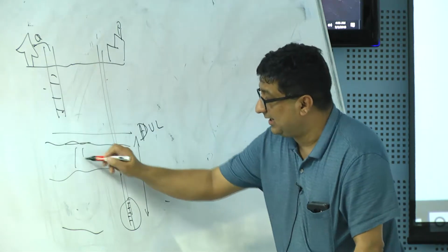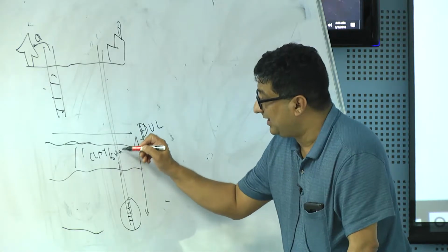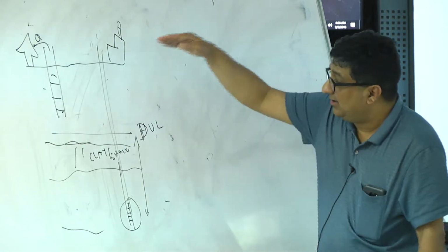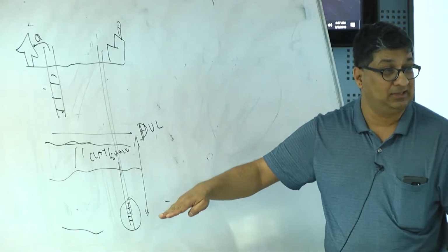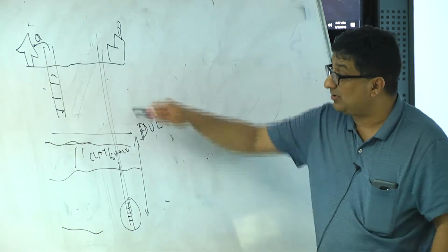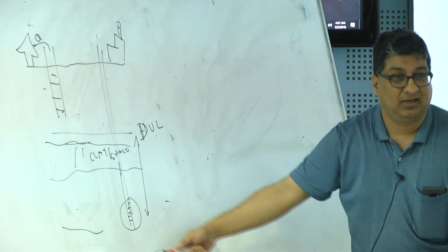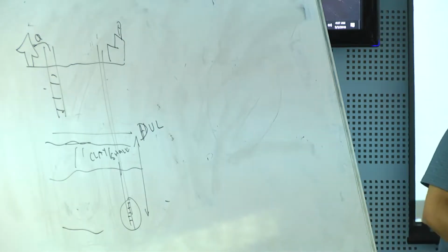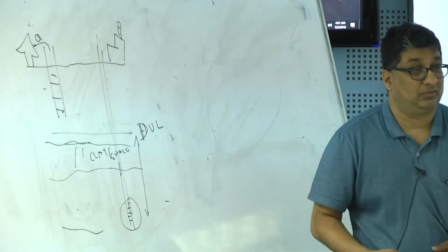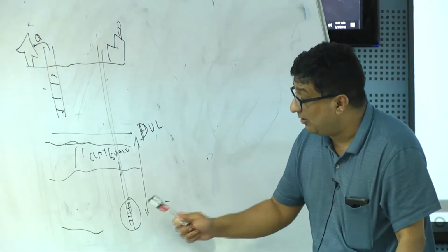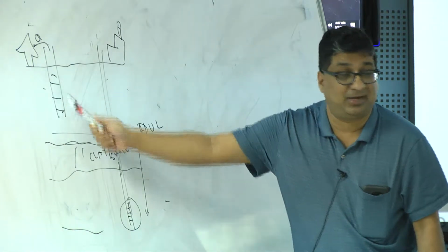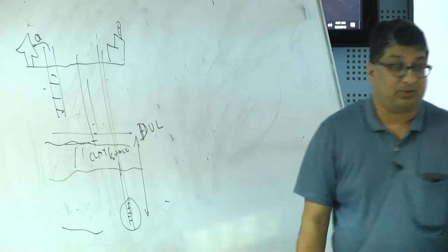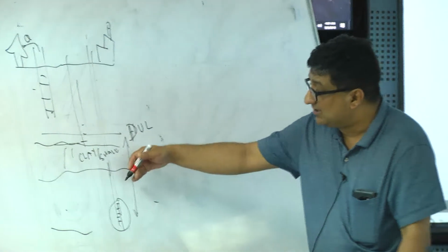There could be a clay liner here or a shale, something very low permeability, and you basically make your case by saying, okay, I want to inject in a deep well, and before I get the permit, I have to make sure that my well is constructed so that it can withstand the pressures that I experience when I go that deep. I'm going several thousand feet deep, like 1,500 to 2,000 feet deep. I need to have a well that can withstand that overburden pressure, but also make sure that whatever I inject here will not contaminate the superficial aquifer. If I say I'm going to inject here, I will not get a permit because I'm in the usable aquifer zone. So I have to go much deeper, and I have to make a case.